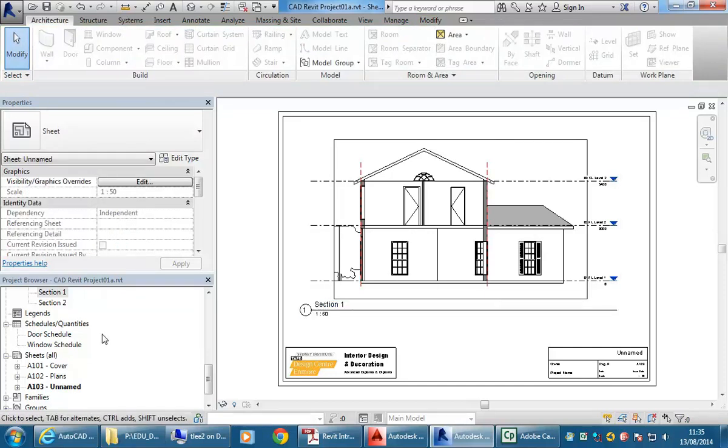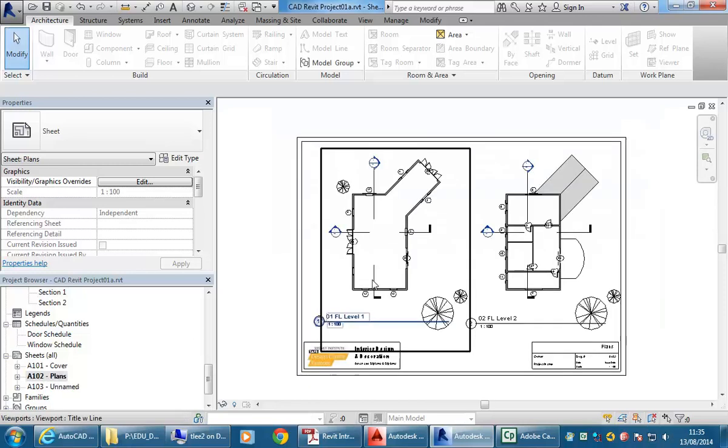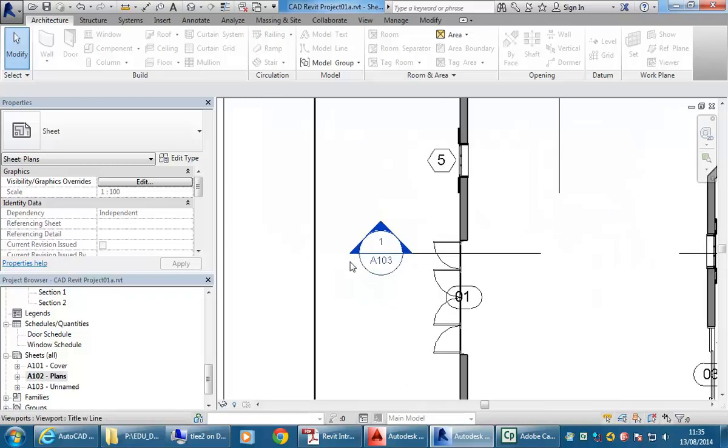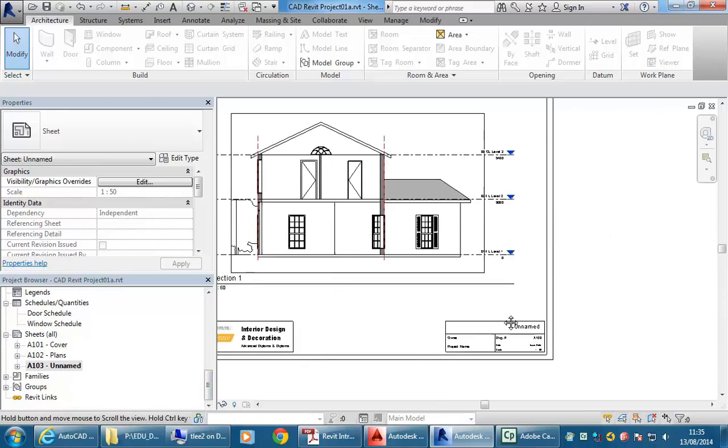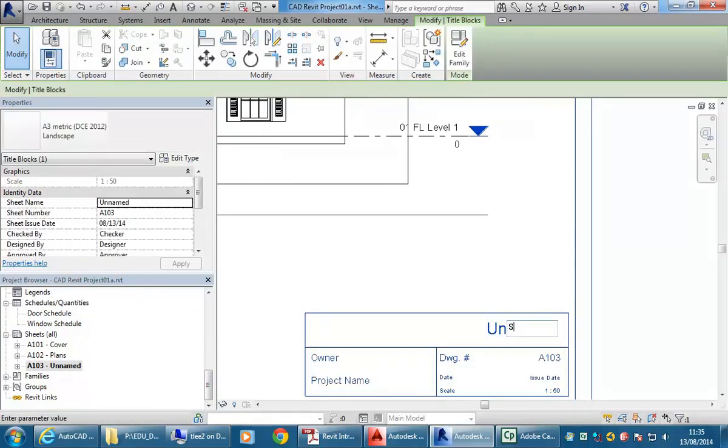So we've got the section there, and then the final thing I want to show you, if I go back to the plan, now the referencing's done. So you might have been looking at your section line, seeing the dash there inside your section marker, and not knowing how to change those numbers. It's only when you put them onto sheets that those will then be done for you automatically. You don't need to do your own referencing, which is a massive thing. Having to do referencing manually is really time consuming. And so again, I could change this name, but that's not so important.